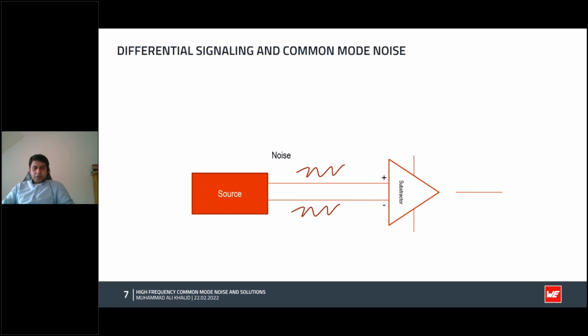In reality, there are always minute differences on the lines. For example, these could be voltage or impedance differences on the two conductors, or a small delay in the switching times on both lines. These small mismatches become more pronounced with increasingly high clock frequencies. Thus, the signals used in modern data and telecommunications are a serious potential source of RF interference, and these signals can also influence other devices and systems nearby.